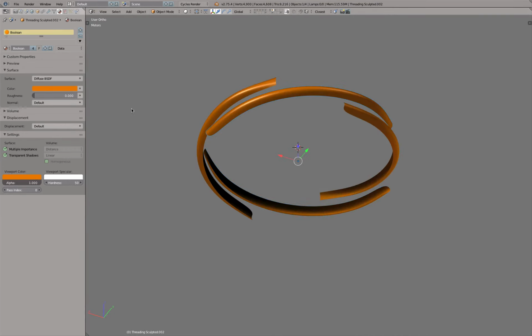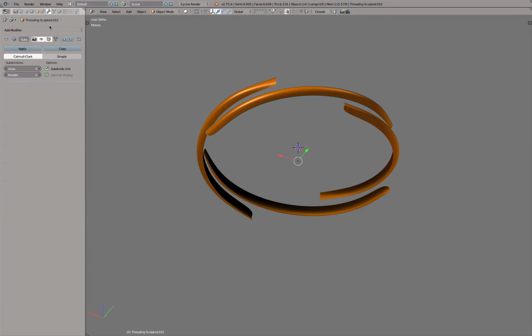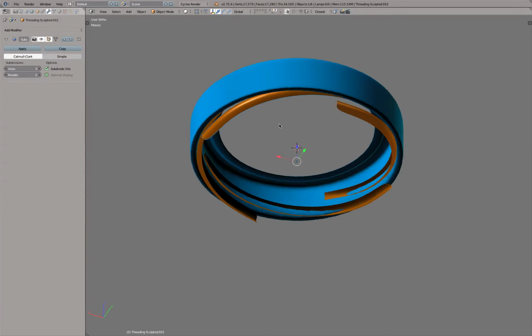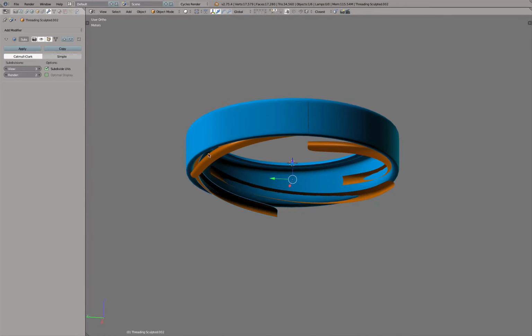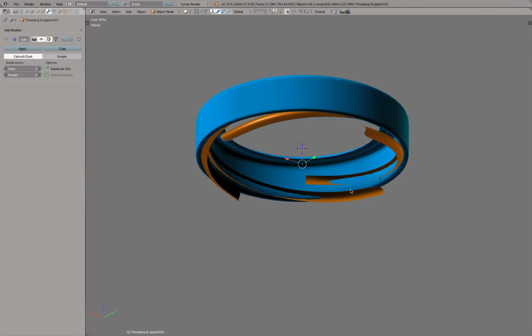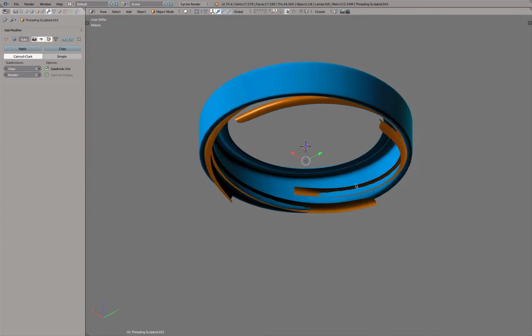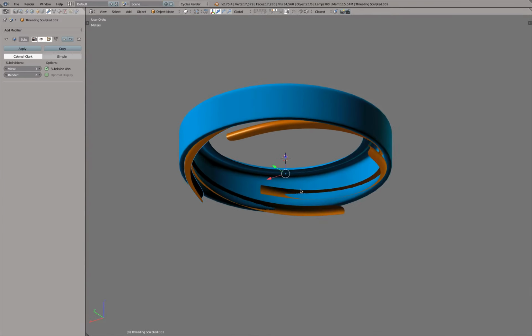Now this threading, we can actually cut out this silicone insert. And you see kind of like where the orange part intersects with the blue part. And that's all we need to have a secure lock. So instead of selecting all these objects, again, we can go and say U, difference. Now with the bottle we added, here we remove, and threading.